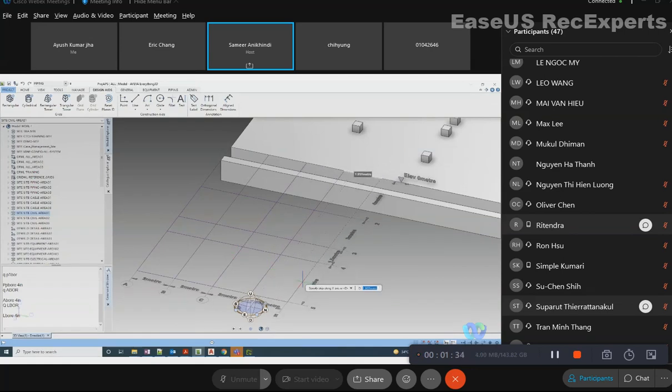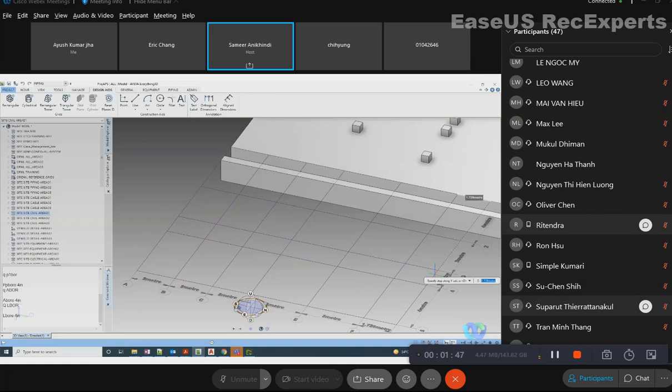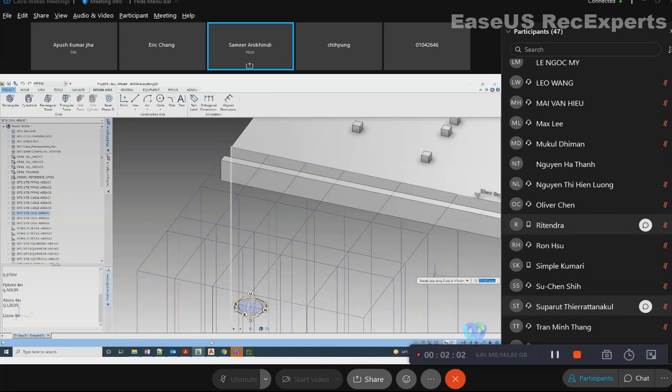And I want 2 grids of 3 meter each. 2 X 3, I am pressing X, okay? So once finished, you can press plain enter without entering inputs of Y. So until you keep on providing the input to Y, it will keep on making. But once you stop input and press enter, it will enter into Z direction. See.